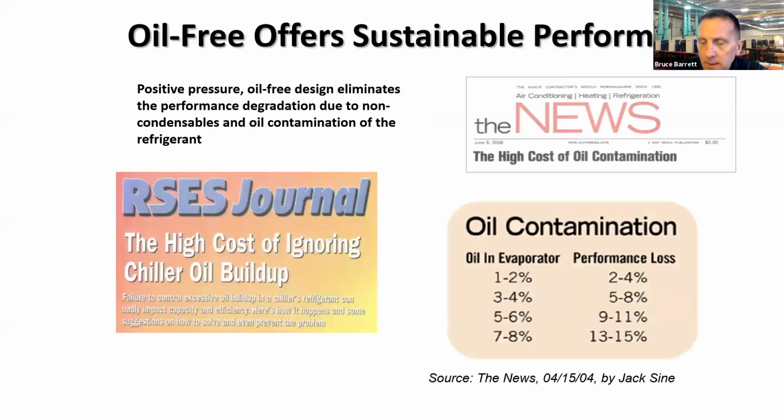It's been well documented through the industry and really through my experience. When you have oil in your system, whether it's air cooled or water cooled, your heat transfer properties will lessen over time. In other words, your approach temperatures from refrigerant to water side get worse. Well published in a lot of the trade journals. If you want the full study, go totally nerd out on impact of oil, I can provide that study. Again, it's an ASHRAE study.